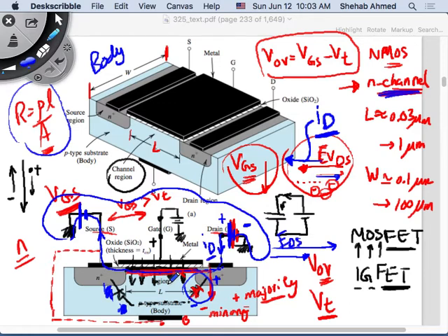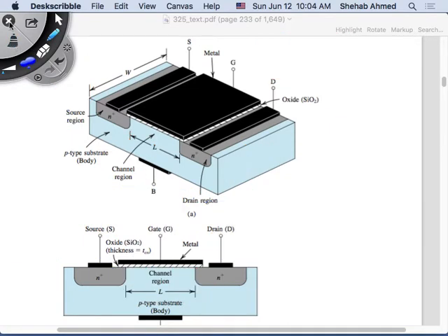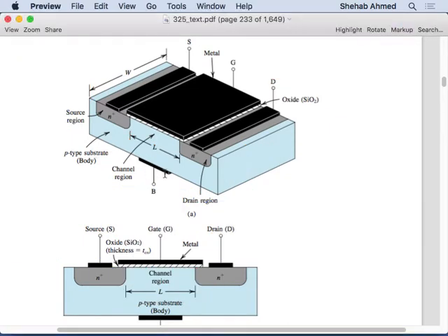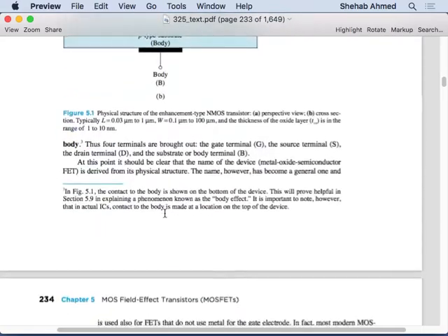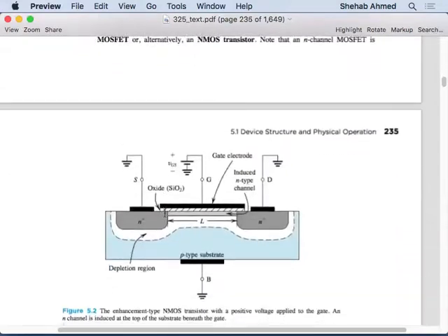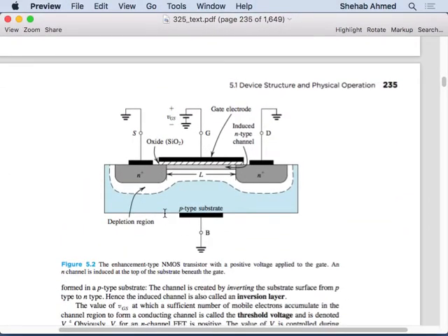So operation of this device, everybody's at least okay with it. Do you understand why this gate is merely a control signal? I think there's a picture with this depletion layer drawn on top. This is what we were talking about. Here's the channel created, but no current flowing yet. This is the case where my drain to source voltage is still ground. We went through that. This is the case where I've created the depletion layer, pulled the minority electrons to the top, and created the channel.